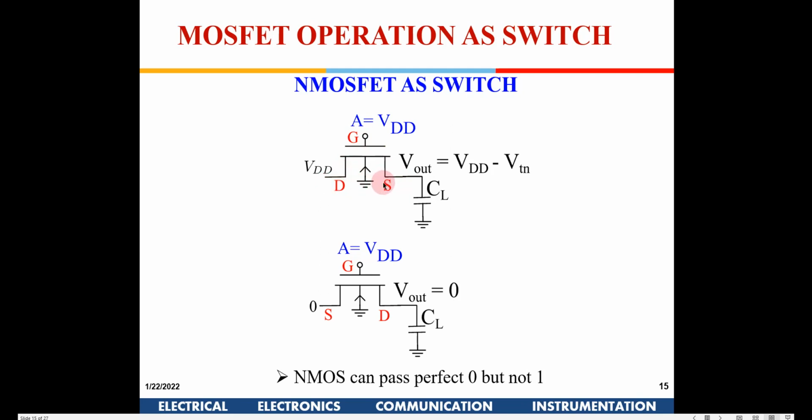That is the reason I call this the source, because this is an N MOSFET and the majority carriers are electrons. The place where the majority carriers start from is called the source. So listen carefully, this is an N MOSFET, majority carriers are electrons, and the flow of electrons starts from the source to the drain. That is why this is known as the source in this case.